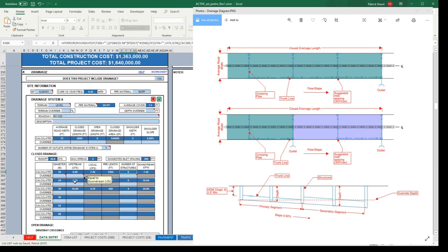So that is basically kind of like a budget. You just transition that downstream to the next pipe going right here, and then that's deducted from the capacity of that 24-inch pipe in order to figure out, all right, well, the 24-inch pipe can handle an additional 8.59 CFS of the rest of that's coming down from the rest of the network.